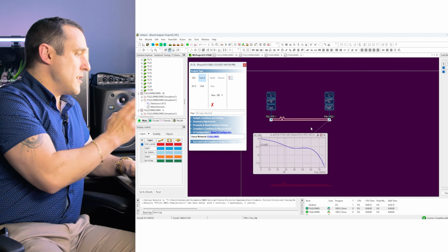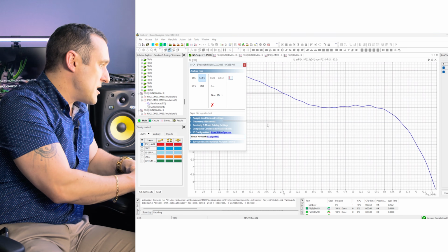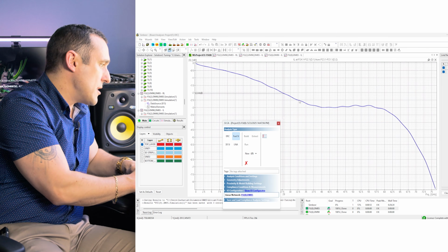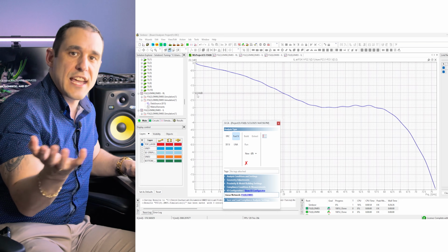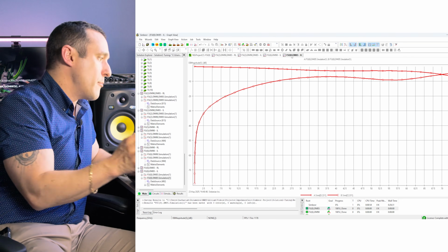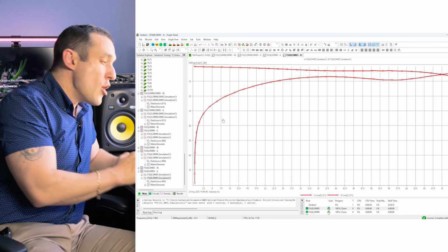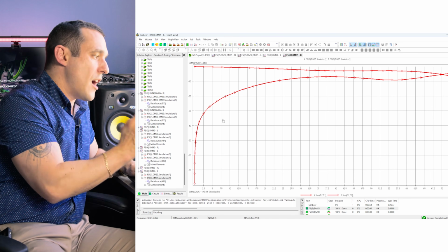Now here you can see the insertion loss plot if I just bring it up and maximize it, and you can see about what the loss was at 28 gigahertz. It's basically -2 dB across the entire line. But here, when I overlay the mode conversion S parameter, that same SCD21 S parameter, we basically see the same thing, but not as severe.